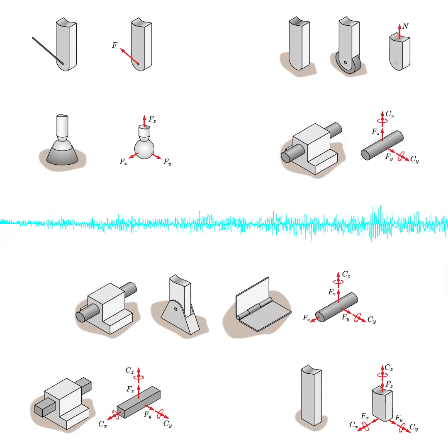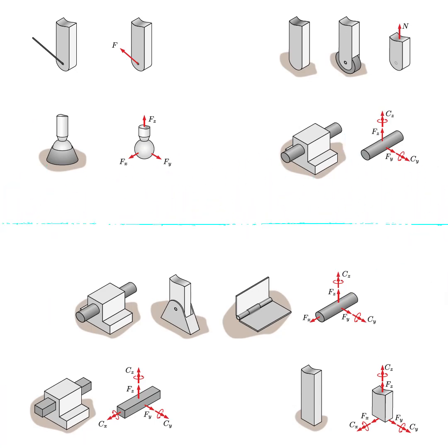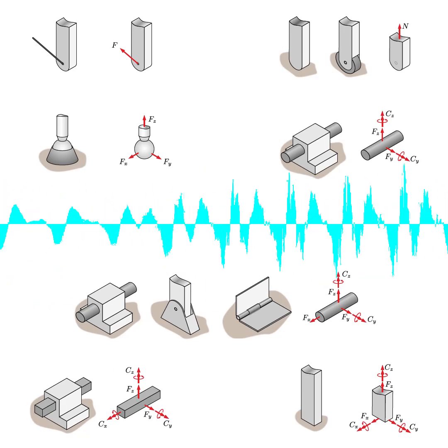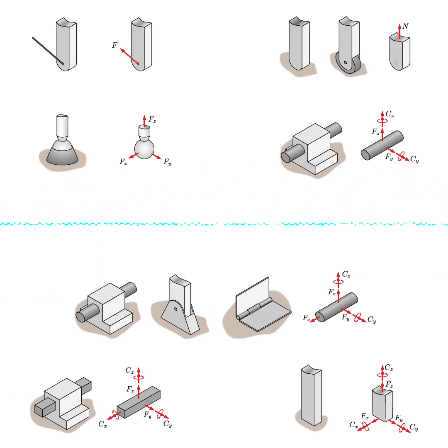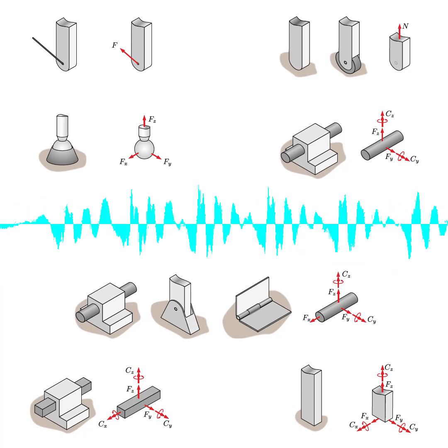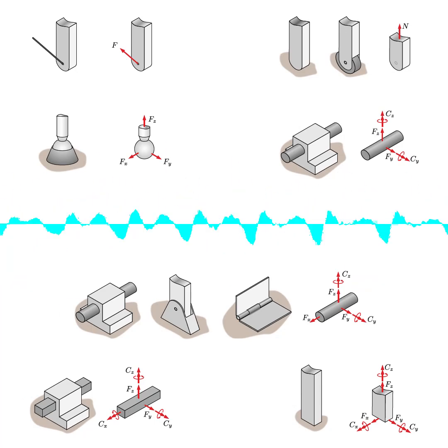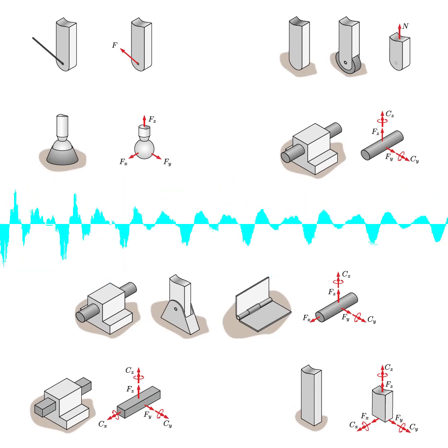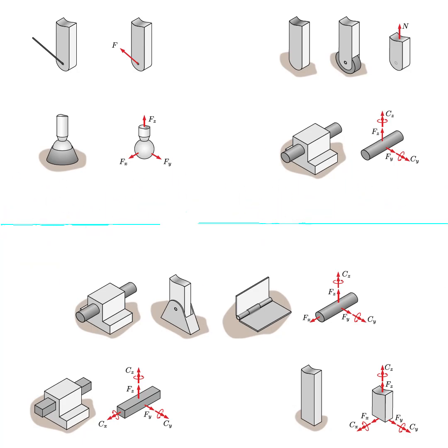All right, and finally, step 5 is to label the diagram. What kind of information are we including in those labels? Okay, so we need to label all of our forces and moments, both the applied loads that we identified in step 3 and the unknown reaction forces and moments from step 4. Include their magnitudes if we know them, their directions, and then any relevant dimensions or angles on the diagram. So really just create that full visual picture of the problem.